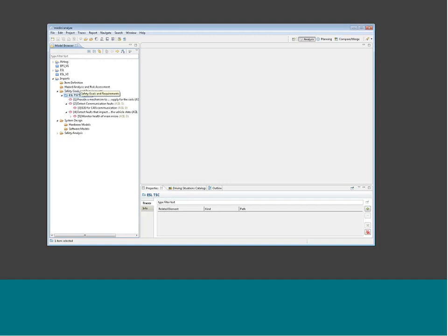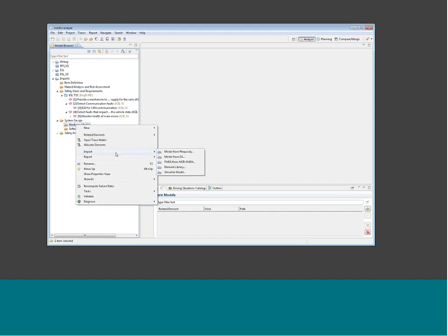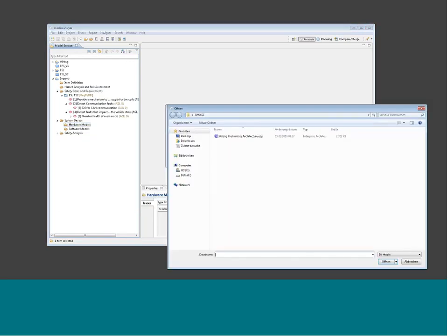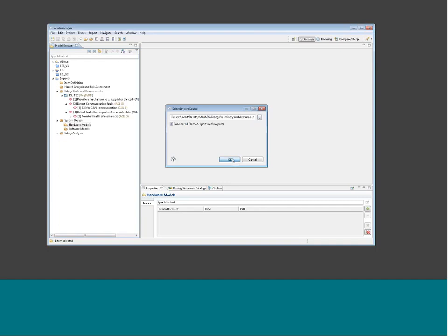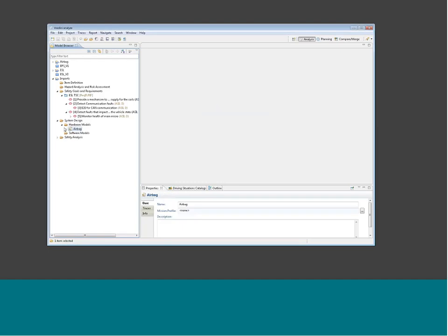Next, I would like to show, as we have seen that we have the SysML modeling inside of Medini. Typically, these SysML models already exist in other tools, so we can just go ahead and import these SysML models either from Enterprise Architect. So this is again a file-based approach. Internally, these Enterprise Architect files are database files which you can analyze and import into our own SysML format. So you can see I have more or less imported the structure of this Enterprise Architect file. Everything which is not of interest for us or which we do not support, like use cases or actors, we just skip during this import.